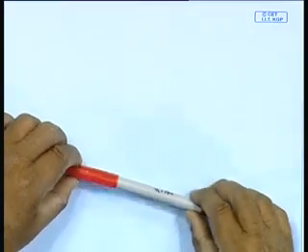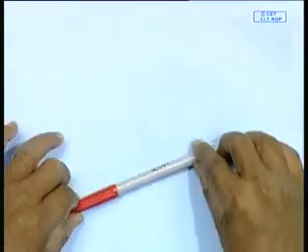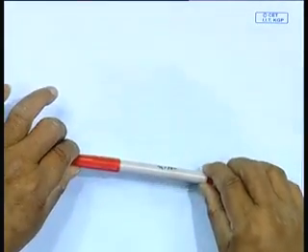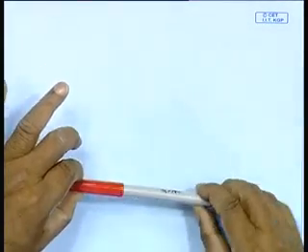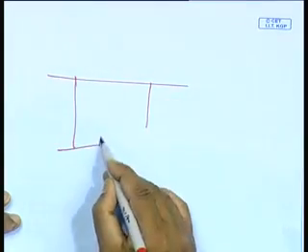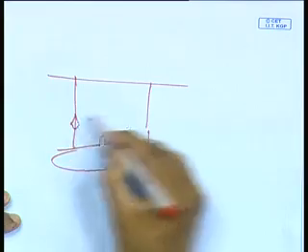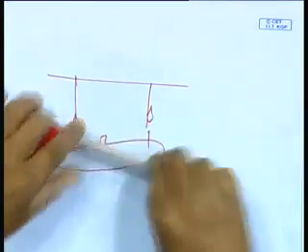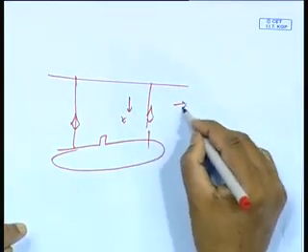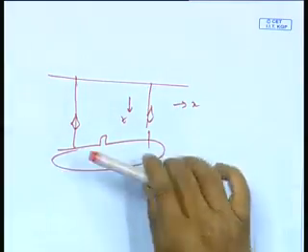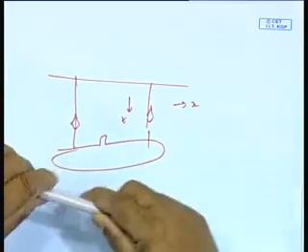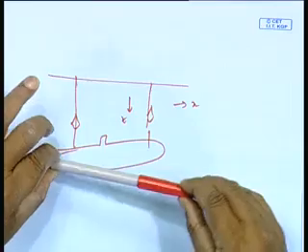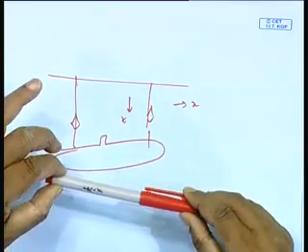I just want to tell you at the very end what happens for submarines. If you look at this, these are my horizontal plane motions, but in a submarine you also want to know the vertical plane. So in a submarine, the planar motion mechanism is actually vertical, the submarine model is kept like that, where I can oscillate it this way. I can oscillate it in the vertical plane, this is my z, this is my x. But suppose the body is kept this way, this is very interesting, in a submerged body I keep it this way and oscillate, but if I want yv and so on, all I do is turn it this way and oscillate it.